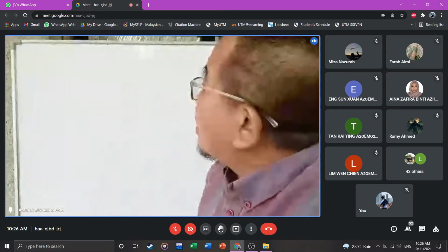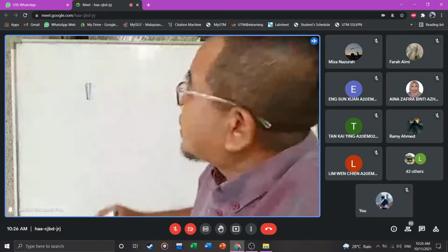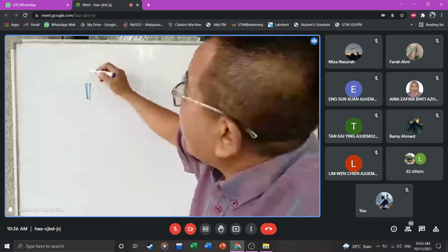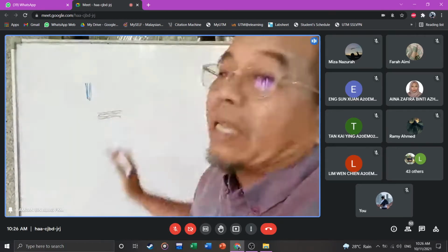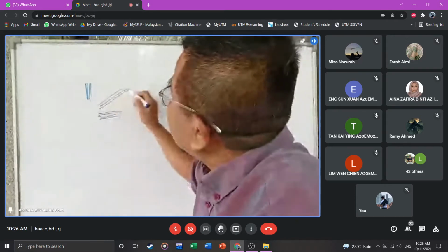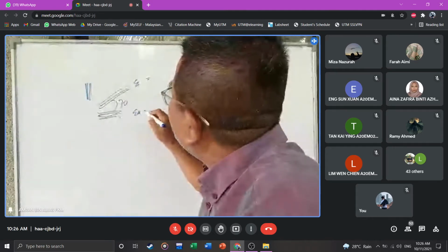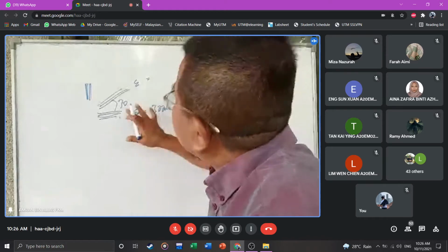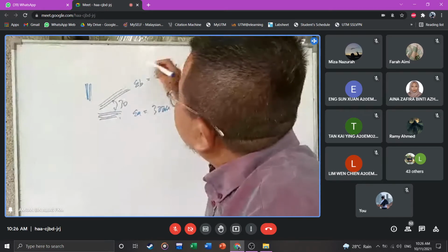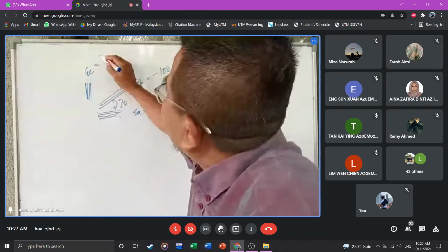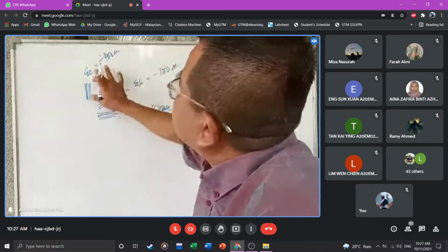So now we know the strain gauge. We put it in the y direction on the surface of the beam, we get a strain in the y direction. This is just a symbol. Put it in the x direction, we get a strain in the x direction. We put one at 30 degrees, so we get EA. Let's say EA is 300 microstrain, EB here we get minus 100 microstrain, and EC here we get minus 400 microstrain. Let's say this is the value.